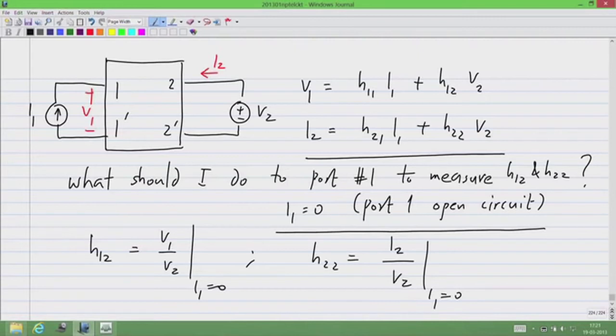Now, traditionally there are components known as bipolar junction transistors which are used to make amplifiers. So those were described with H parameters. And there is a question of why it is hybrid. If you look at Y parameters, all the Y parameters have dimensions of conductances. And Z parameters, all of them have dimensions of resistance. Then these H parameters, the dimensions are all mixed up. One of them is a resistance, one of them is a conductance, and two of them have no dimensions. So that's why it's called hybrid.